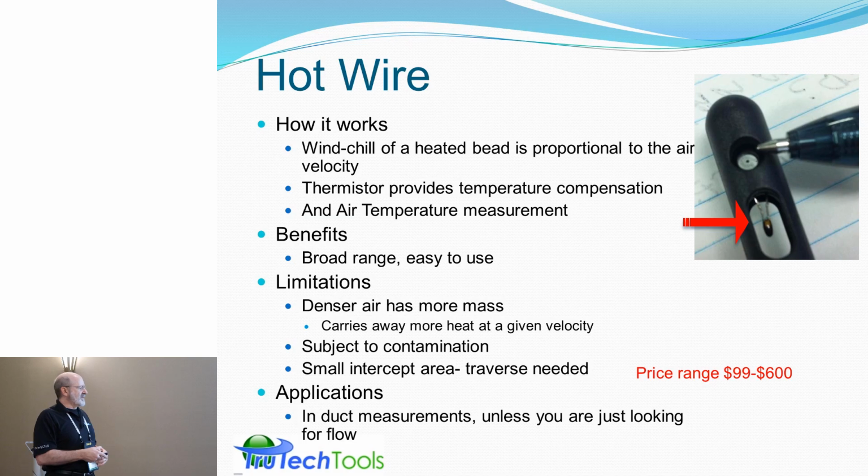And I say in-duct measurements are the prime application for it, unless you're just looking to see if flow is present for leakage. You can use it on supplies and returns, but it requires an awful lot of care and measurement. So generally, I don't recommend it. I may change my opinion on that.